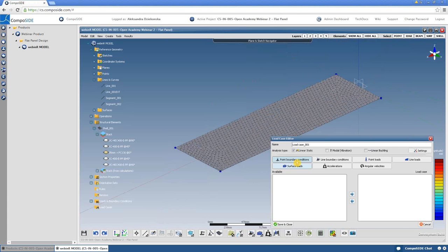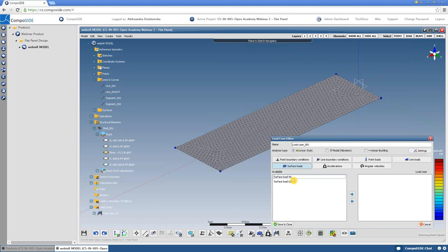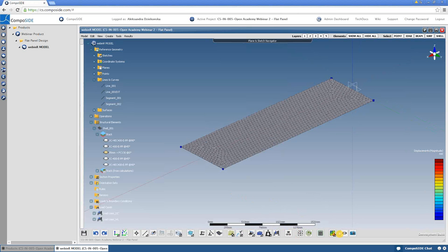Okay. One more thing I need to do before I can calculate. I need to prepare a load case. The first one is the working. And the second one will be the ultimate. As you can see, we handle different analysis types. It's linear analysis, it's buckling analysis, vibration with pre-stress, which gives pretty good spectrum of the different options. Okay, I'm just sending the load cases to be calculated.